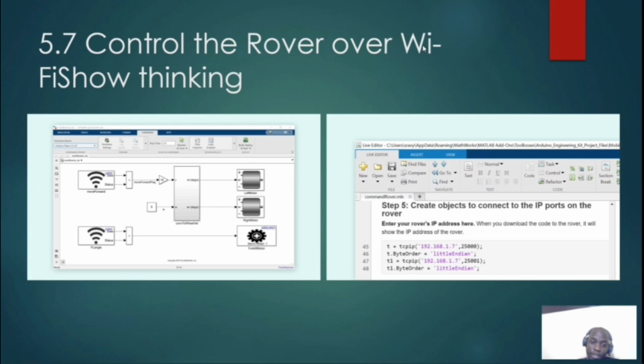And for the final piece of the puzzle, our robot gets position information from two sources: the webcam via the Wi-Fi, and its motor encoders, which provide odometry based on wheel rotation. Both have strengths and weaknesses. Vision is good for global position, but can be noisy or lost. Encoders are good for relative movement, but can drift over time.